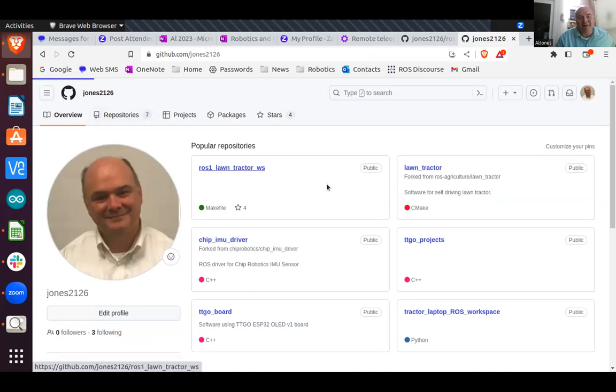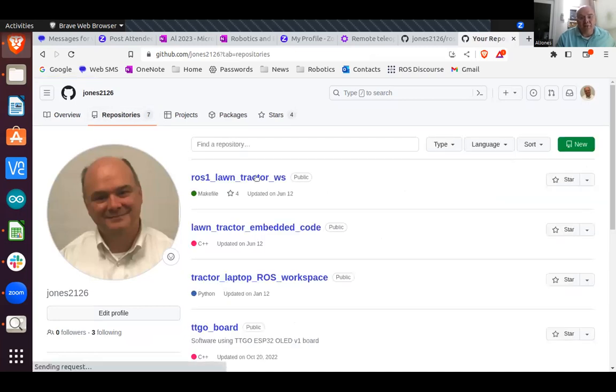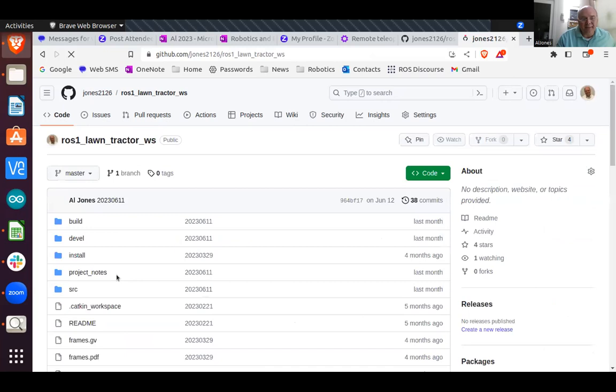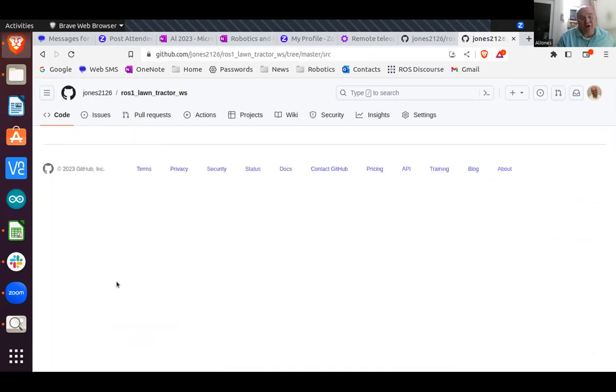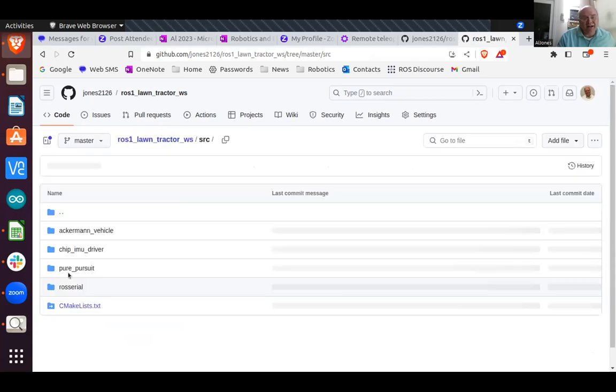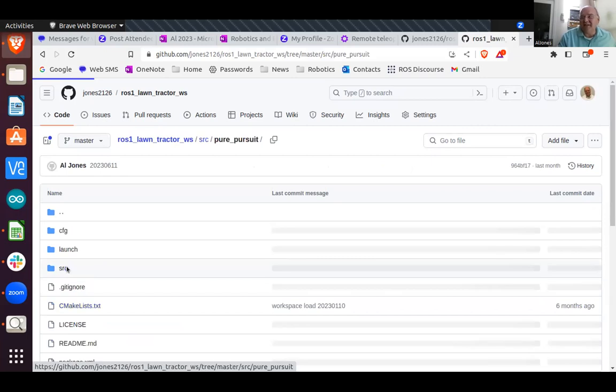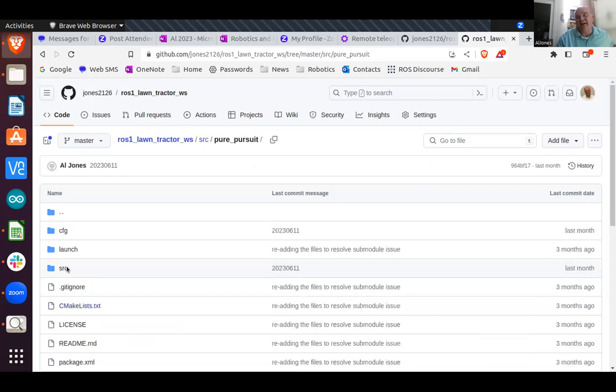Right now, mine is speed control, because this pure pursuit algorithm that we're trying to use is dependent on the current velocity of the vehicle. And if that goes up and down, then obviously it's going to calculate a different steering angle for the vehicle to follow.